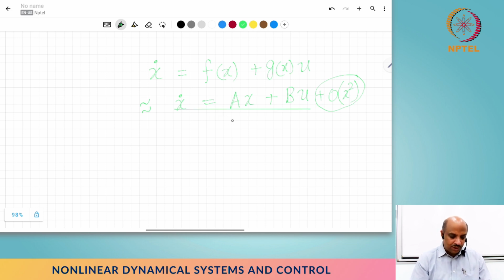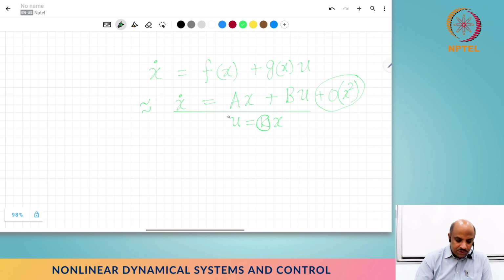We know how to design a full state feedback controller, and more general techniques through output control, or for that matter sometimes dynamic control. We have those techniques. So if we know that technique, can we not somehow keep changing this k, so that whenever a changes, k changes too? Why does a change? Because as x changes, f of x changes, and then the derivative, the gradient, the Jacobian of that is going to change.